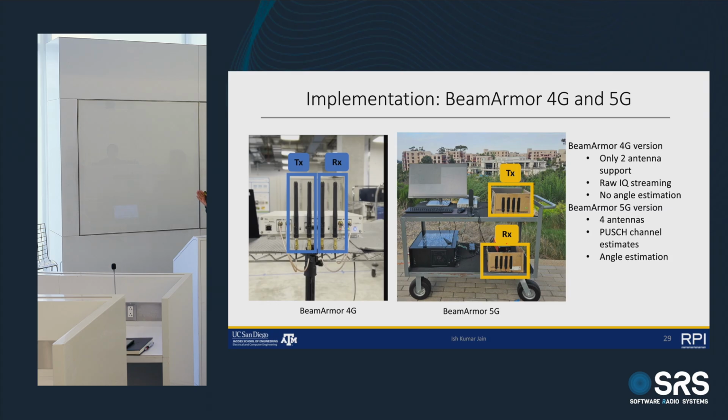We can do sensing and angle estimation, and as long as we have the real-time channel estimated from the antennas, that will capture the effect of any hardware artifact, and the beamforming or beam nulling will null, or try to null, the artifacts. We have seen that with a realistic setup it works, and we haven't gone too deep into really optimizing the hardware. We just used some commercially available antennas and kept them λ/2 apart for this setup.